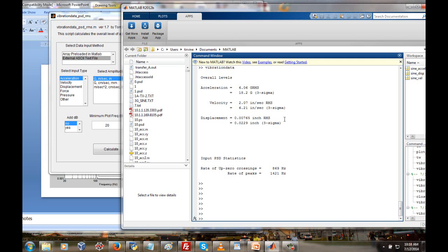That depends in part on the duration of the test, and it also depends on how well the vibration complies with the ideal Gaussian distribution. And always there's some imperfections that come about in the test process. So we could have some deviations from the ideal Gaussian. So just be aware, for example, that you could have higher sigma peaks.